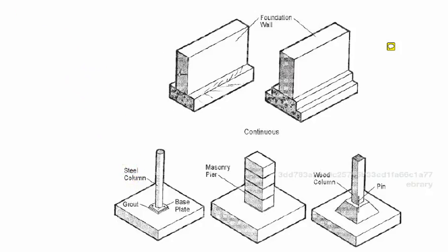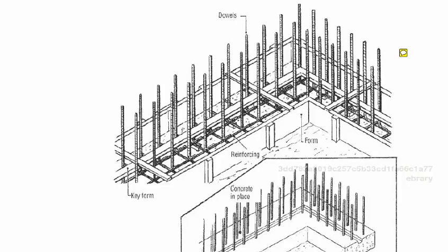When you're building a footing of some sort, remember that you're going to have dowels or rebar coming out of that footing to be able to attach onto, say, the footing walls or the walls that you're setting the footing on, or the column that you're setting on. And again, placing that steel has to be done accurately. You need to have the proper spacing in order for it to carry the structural loads that it's designed for. Even more importantly, well, just as important, is that you need to make sure that steel is accurate.